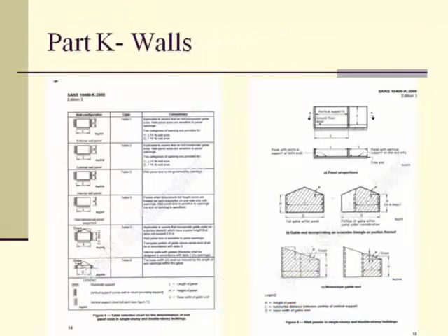Some further little details depicting the elevations of walls and what you need to show in your elevations. On the right hand side of the picture in the middle, there's 2 elevations there with a dotted line showing where the connection is on that plane, with a wall behind, which in plan just above indicates where that wall intersects with the one in elevation. You now need to show that, because the length that you're allowed before you have a turn, based on the fact that this is now going to be more than 2.4 meters in height, if you're going to take it up as a gable, you have to show what intervention you're going to have to not comply with the 2.4 meter height limitation. It's things you just haven't really had to think about before. It's not rocket science, but it's just a little bit more detail.